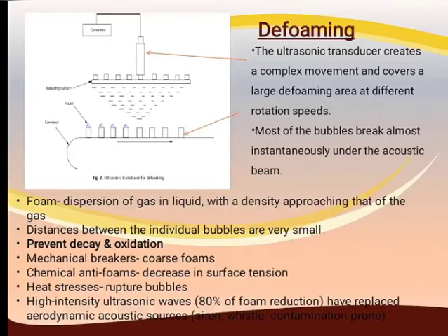Defoaming. The ultrasonic transducer creates a complex movement and covers a large defoaming area at different rotation speeds. Most of the bubbles break almost instantaneously under the acoustic beam. Foam is a dispersion of gas in liquid with a density approaching that of the gas. Distances between the individual bubbles are very small, which prevents decay and oxidation.